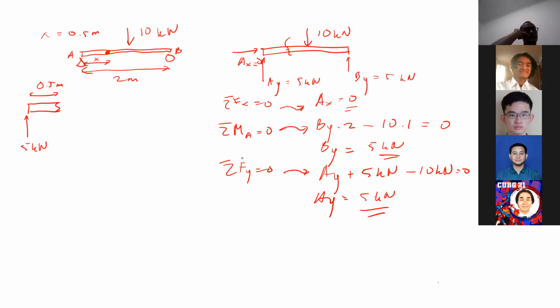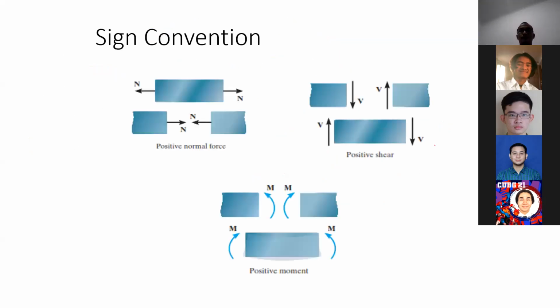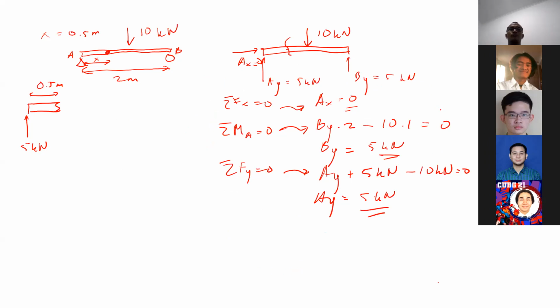For this case, this particular section, the positive direction is supposed to be going downwards or upwards. Remember here, for shear force, it's supposed to be clockwise. So this one is upwards or downwards? Downwards. Downwards, correct. Because it's supposed to be clockwise. Downwards, yes, will give you clockwise moment. Okay, so it's correct. It's downwards. What else that we have to put there, Mario?